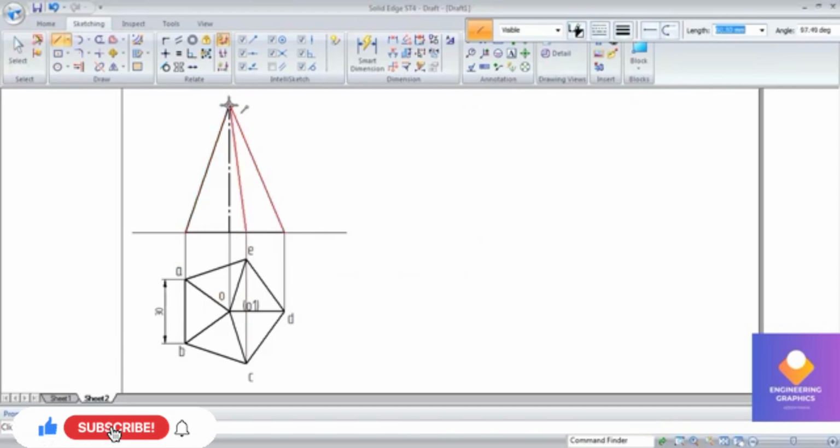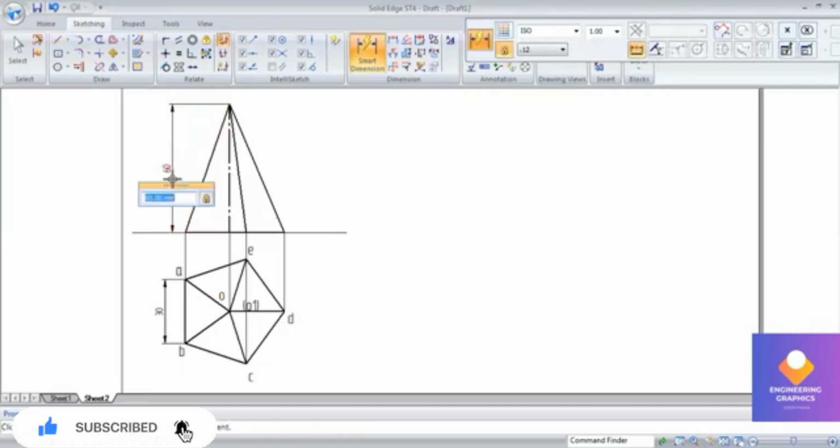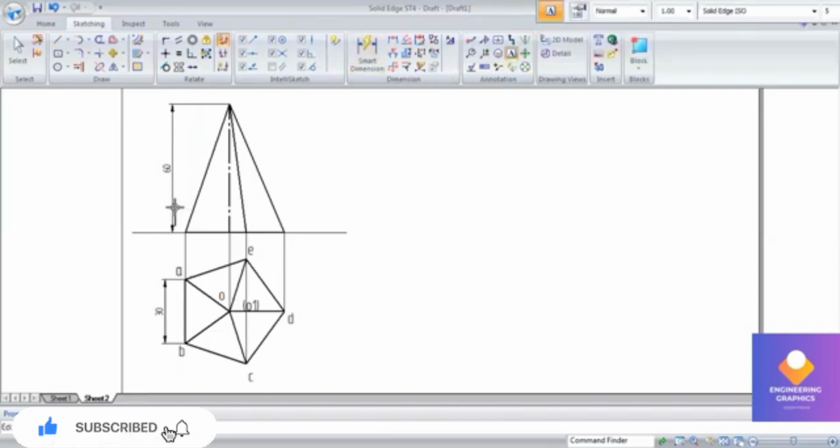We can connect it to get the front view of the pyramid. So the front view of the pyramid is a triangular face. You can show the dimensions, and here we know that the pyramids will be drawn with the slant edge length, the true length. So first we have to find out the true length here. Before that I'll be mentioning its front view notations.